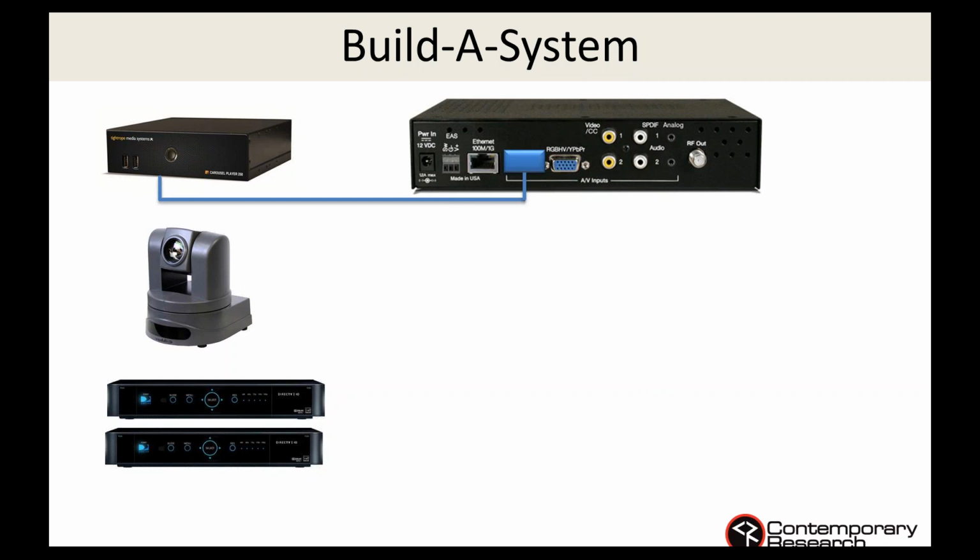I'll have a blog in the other discussion on how you can use HDMI with modulators, where I get more into dealing with HDCP and different techniques. The nice thing in most of our systems, digital signage and a lot of the sources we have, is that HDCP is not really involved. This isn't consumer stuff. This is commercial stuff. So HDMI is great though, because when you run it, the audio connections and the video connections are all together in one cable. So you run it there and you're there.